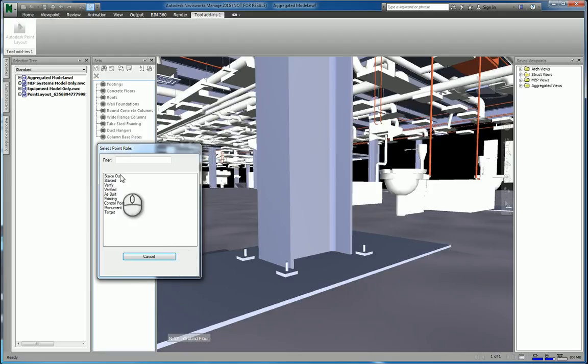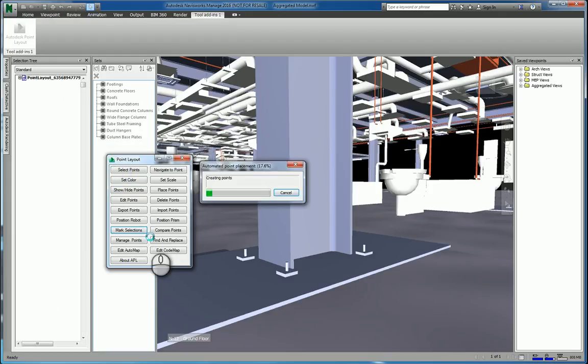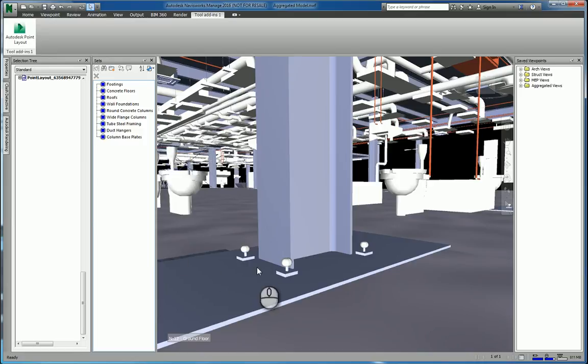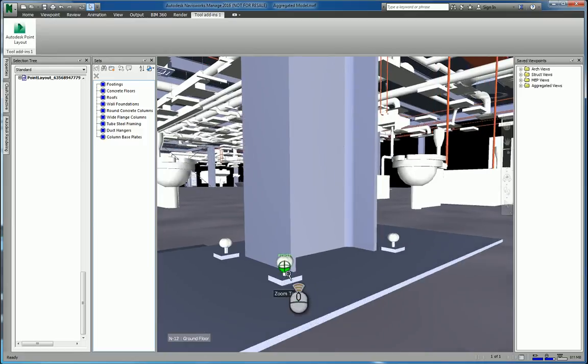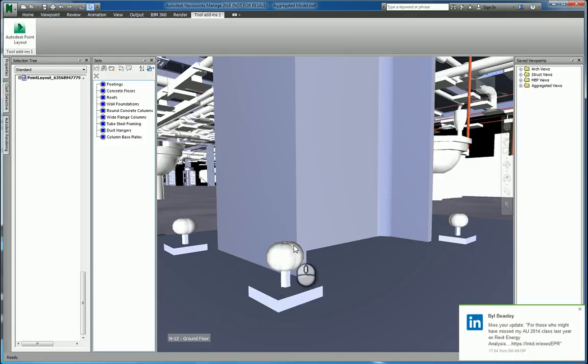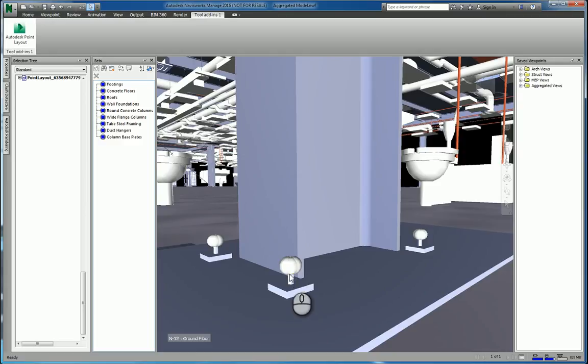And we want them as stakeouts. It will run through the entire model, select all those 3D objects, and place those points, as you can see. Because I chose geometry, it looked at that 3D extrusion, if you will, and placed as many points as it can around the perimeter of the circle of that cylinder. So again, you can go through and delete the ones you don't need.